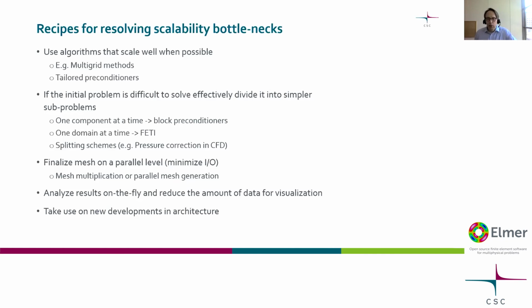That generates domain decomposition methods, and in Elmer we have a FETI method, which I didn't mention, but its weak scaling is superb. The challenge is to find large enough linear cases where it is applicable. So if you have huge cases, that FETI method, where you solve one domain at a time and then have a different equation to combine those solutions, is maybe of use for you.